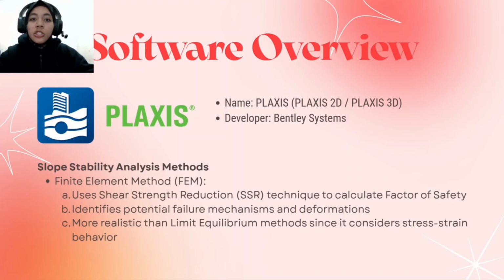It uses the shear strength reduction, SSR, technique to calculate the factor of safety, and identifies potential failure mechanisms and any deformations. It is much more realistic than the limit equilibrium method since it considers stress-strain behavior.